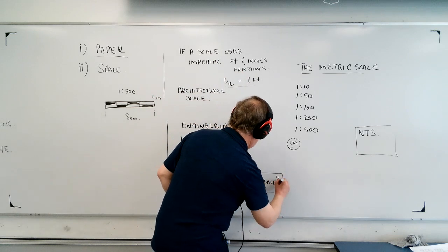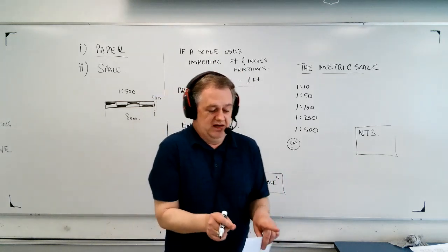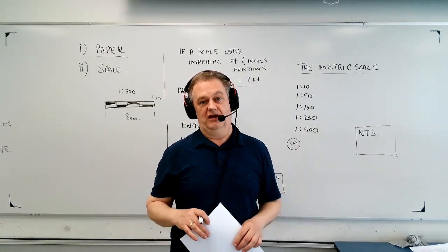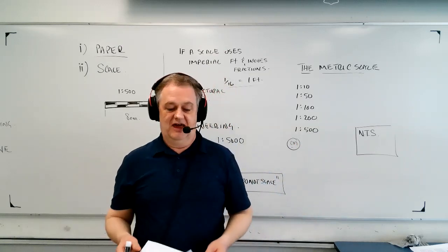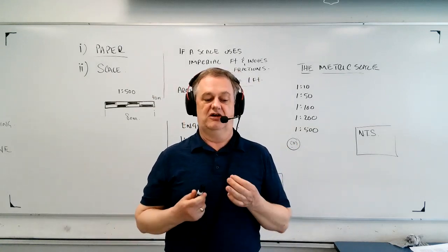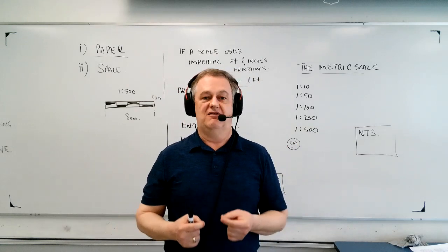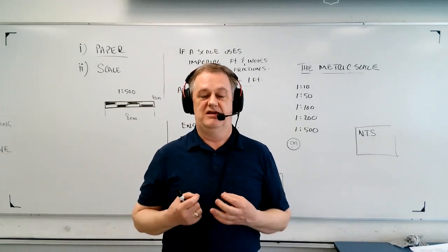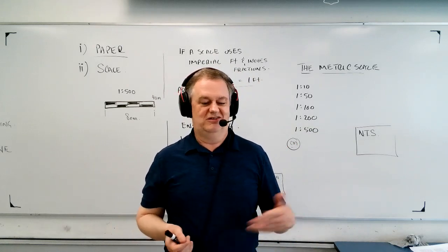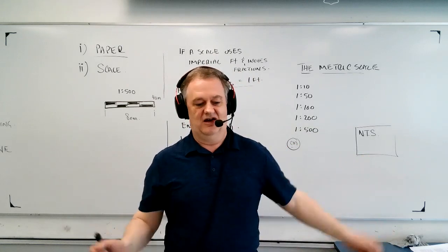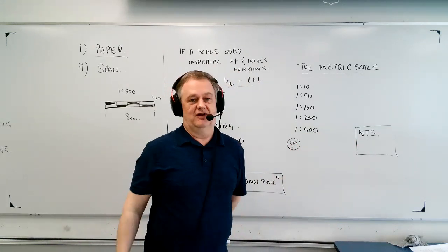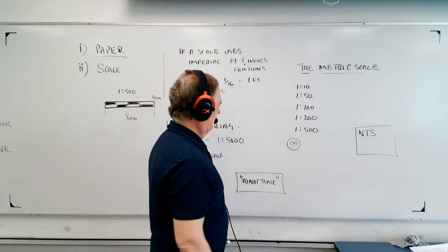In other words, don't try to take a reading on one part and then apply it to something else. So they specifically tell you, don't try to scale this drawing. And usually in cases like that, there are notes in the specifications that say it is the contractor's responsibility to make a site visit and make all of the necessary measurements in person. They don't want somebody just doing a quick estimate, scaling off and saying it's about that. They say, no, you have to actually make a site visit, check this stuff off, and make sure that it's right, okay?